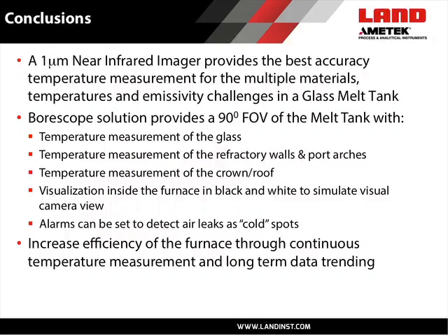The NIR-B thermal imaging camera provides the best accuracy temperature measurements of the multiple materials that we find in glass tanks. The very wide angle through the wall borescope lens sees a 90-degree field of view, allowing you to see both the materials within the tank, refractory materials, the crown, the port arches.